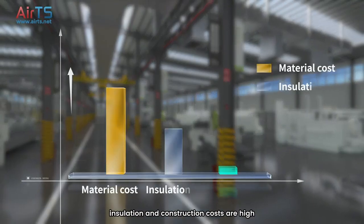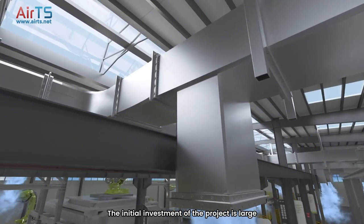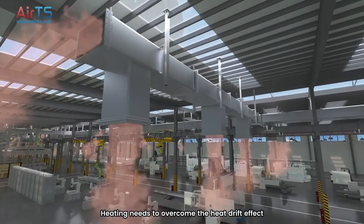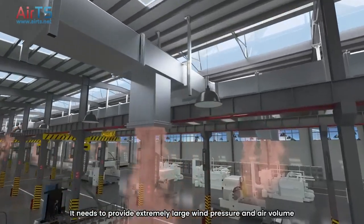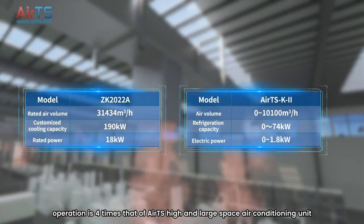Air duct materials, insulation, and construction costs are high, especially in high-rise factories that involve high-altitude operations. The initial investment of the project is large, and the wind pressure is attenuated greatly after being transported through long-distance pipelines and turning. Heating needs to overcome the heat drift effect to deliver air to the ground. It needs to provide extremely large wind pressure and air volume, and the power consumption is high. The electric energy consumption of fan operation is 4 times that of the AirTS high and large space air conditioning unit.